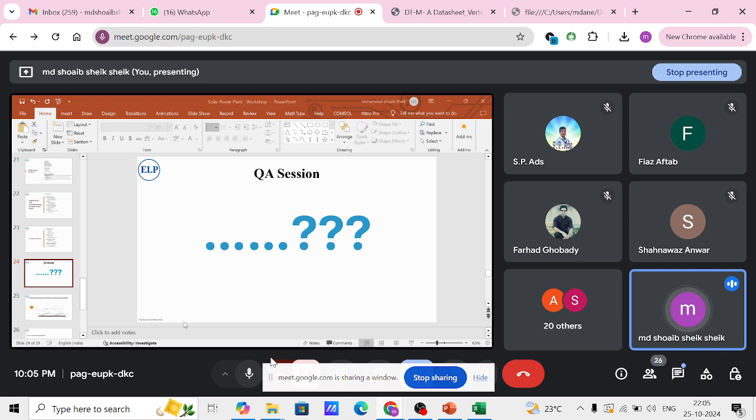It keeps changing, and there is an elevation we have to calculate. The tilt angle gives you an average value, not a completely exact value, and we install according to that average. That's the reason the solar tracking systems, single axis and dual axis tracking mounting systems, have come across. They track according to the sun direction. Next question.